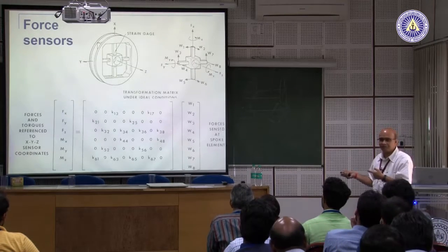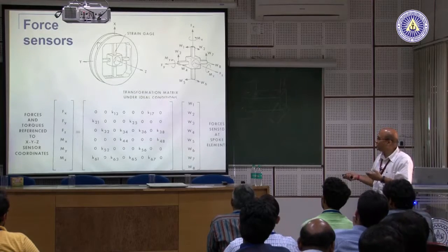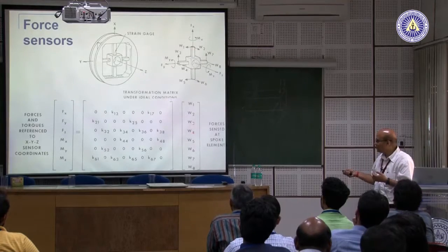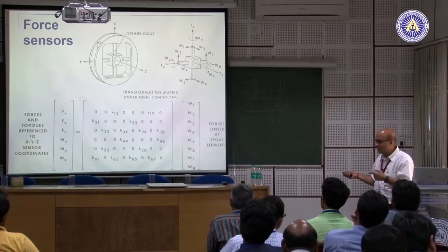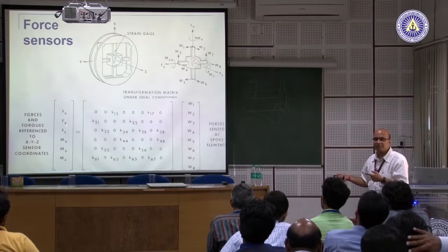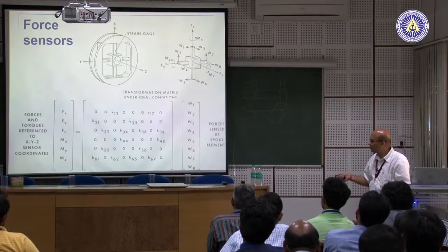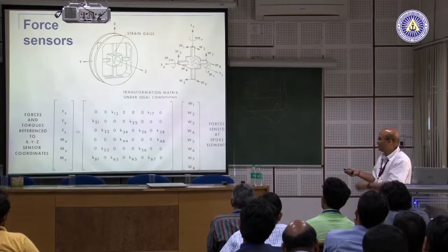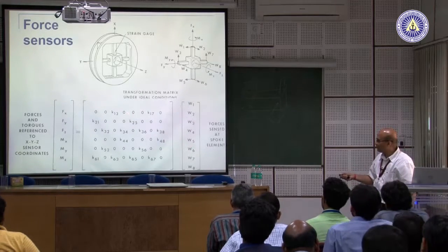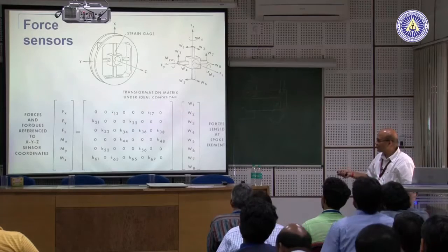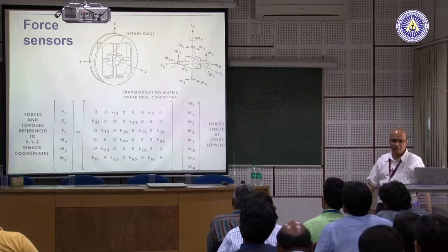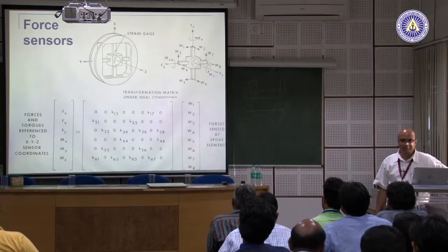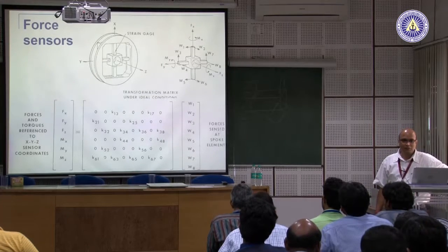Okay. So, once we have this equation, F is equal to gain matrix K into the W's, okay, then the system is calibrated. Okay. So, when it is going to work, if I give an unknown force, we will basically see what is the strain generated here, and then say, okay, this strain is going to cause that force. So, for which I need to invert this one. Okay. So, basically if I want to find W, then it must be equal to the gain matrix K inverse into F. That is what it means. Do you see a problem there?